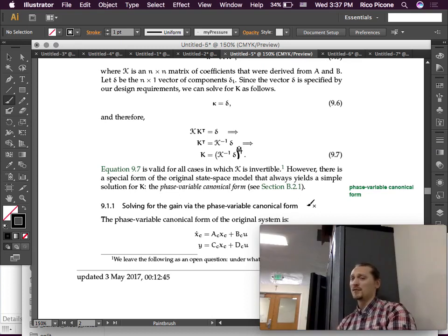The way that we construct state models, it's always an energy storage variable. So it's either going to be a current through an inductor, or a velocity of a mass, or something like that. Something that is intuitive and that physically makes some sense. That's part of why we have always gone from this perspective of state space modeling from the get-go, and not as an afterthought, because I think the state space models that you get are much more informative and more powerful.